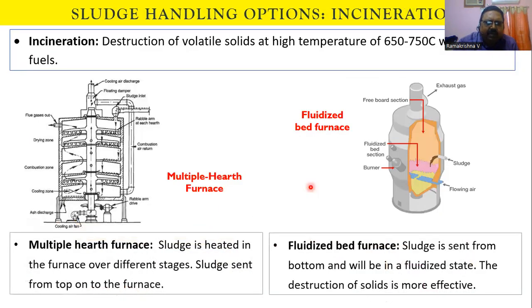And the common option which is used is incineration. Incineration is nothing but destruction of volatile solids at high temperature, at 650 to 750 centigrade, with auxiliary fuels.